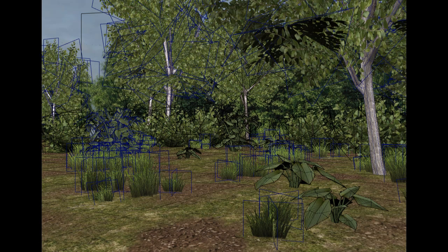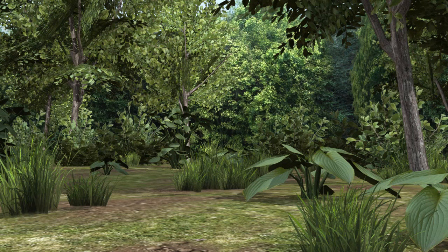The first thing we'll tackle is a tree wall. The term tree wall refers to a flat shape or plane which has a texture map applied to it of a line of trees. Tree walls are usually placed in the far extremities of an environment behind other assets to add a backdrop to the scene cheaply. The player should never usually be able to get too close to tree walls. It's good to keep this in mind when building an environment. This technique can also be used to create a backdrop of buildings, mountains or whatever for the back of your scene.